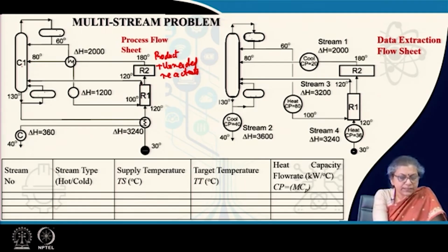Once they come into the distillation column, distillation takes place and we get a top product and a bottom product. The bottom product, part of it definitely has to be recycled back. We know from the reboiler, this is the reboiler, this is the condenser, and the rest of the portion has to be cooled and then it is stored or it is taken for some other purpose.